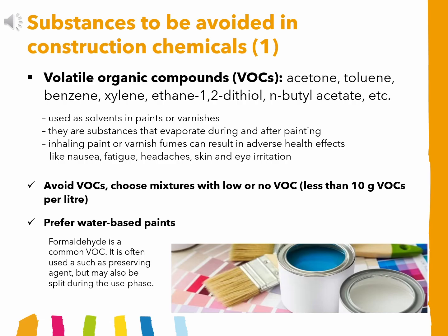The first group is volatile organic compounds, or VOCs. These include substances like acetone, toluene, benzene, and xylene, commonly used in paints and varnishes. VOCs evaporate during and after application, and inhaling the fumes can cause nausea, headaches, and irritation. Whenever possible, choose low VOC or zero VOC products, ideally less than 10 grams per liter, and prefer water-based paints.